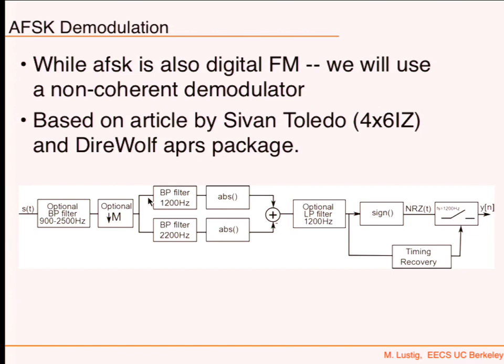So if there is a frequency there, I mean, we kind of did that for the GSM lab, right? We filtered at a particular frequency and then did an absolute value to detect where things are happening. This is kind of what we're doing right now. And remember, even then, we used the filter to be the size of the pulse because we don't want it to leak, right? So it's kind of like a match filter again.